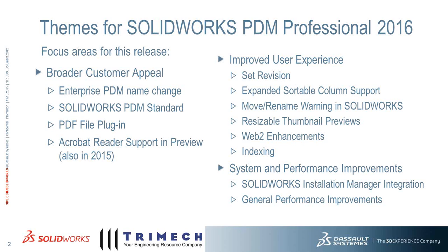We also have some improved user experience interfaces, such as being able to set revisions for documents instead of having to rely on a legacy file workflow, using automatic transitions, trying to detect the revision and then automatically force the system to update using a series of quite complex workflows. Now we have the ability to set the revision as we check in those files, bump up the revision accordingly.